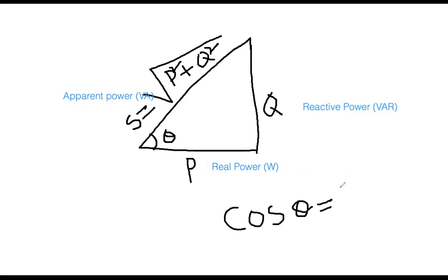And this power factor is P over S. From this triangle, this is cosine theta, so active power over apparent power. Yes, exactly. So therefore, everybody, please try to remember this one. You need this diagram in your head in addition to those equations. That will help you a lot to solve many problems.